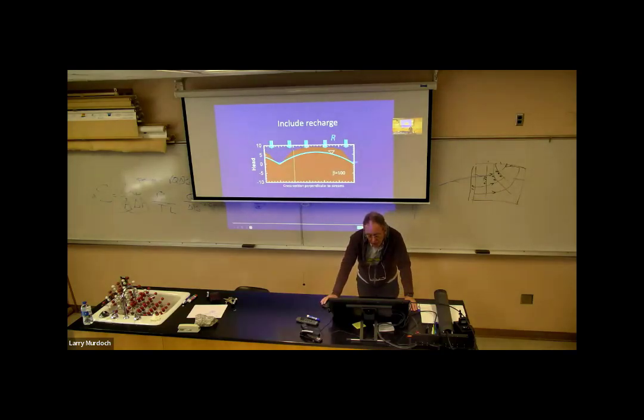Awesome. So what I've been drawing so far has the hydraulic head starting out as flat. Conceptually, you can think of that as the initial conditions, and what we're drawing then is a departure from the initial conditions. But really, the hydraulic heads are not going to be flat in most practical cases. They're going to start out with some kind of hydraulic gradient.